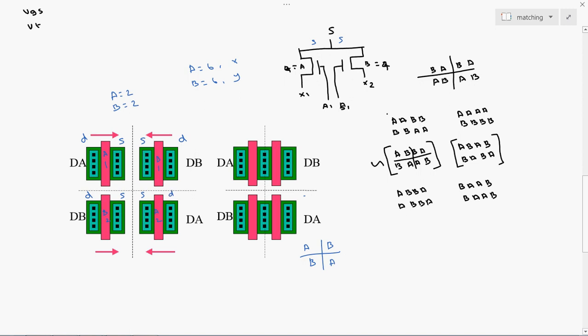So these are the 4 transistor terminals. We are merging the source terminal, common here. Here also we are merging the source terminal, common here. There is a drain terminal, drain terminal, drain terminal, drain terminal. The gate remains the same, so we are not giving any connection to the gate. After finishing the layout, we can take it as a common source. Easily we can finish the routing by adding a metal layer here.